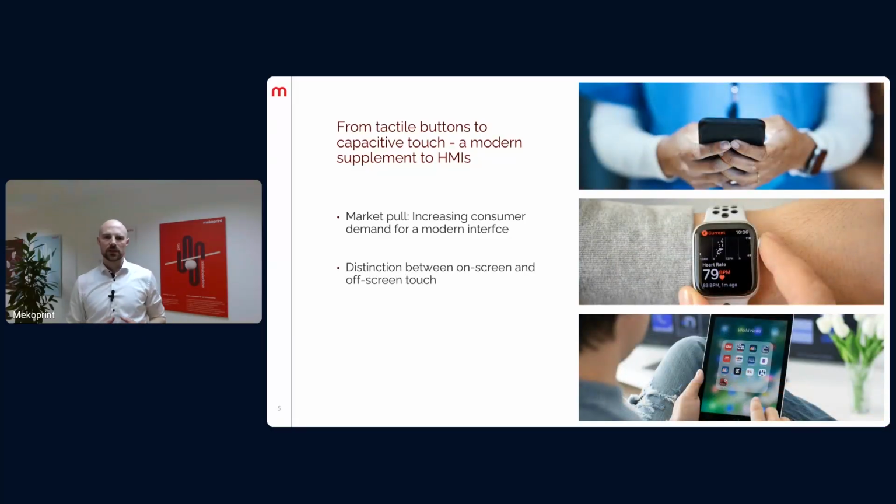Most people associate touch interfaces with smartphones and tablets, and we call that kind of capacitive touch sensor an on-screen sensor. Because it sits in front of a display, the optical requirements for an on-screen touch sensor are very strict, and therefore they need to be produced and bonded in a controlled clean room environment. However, many products cannot carry the cost of such a very cost-intensive on-screen touch solution.